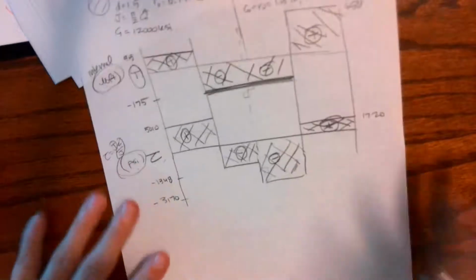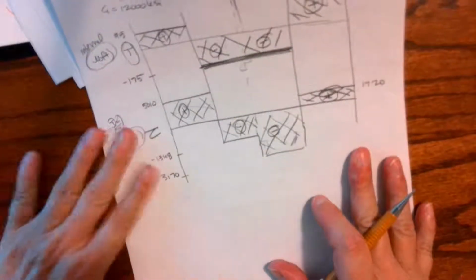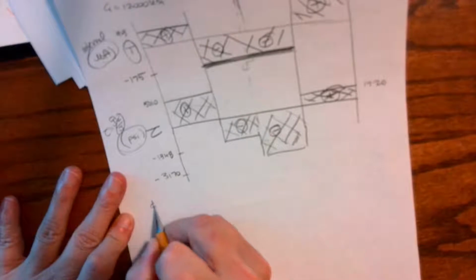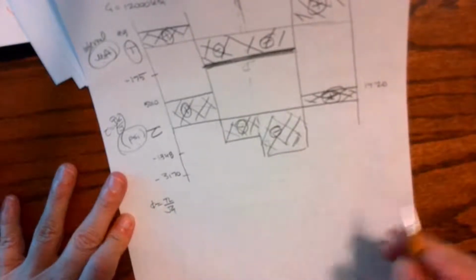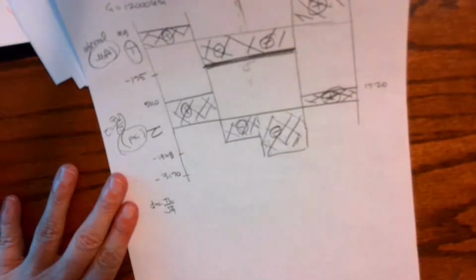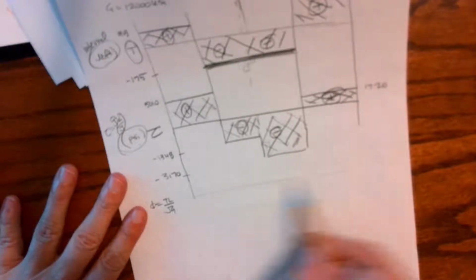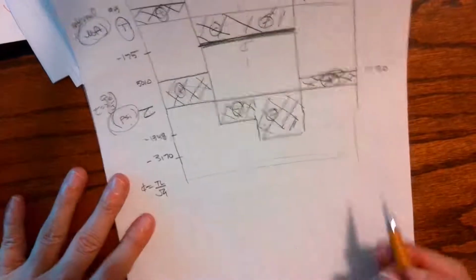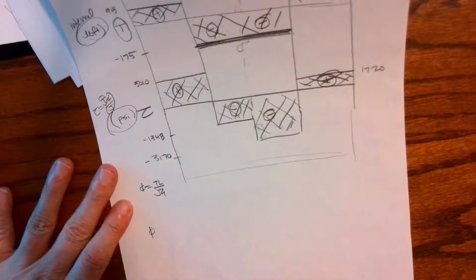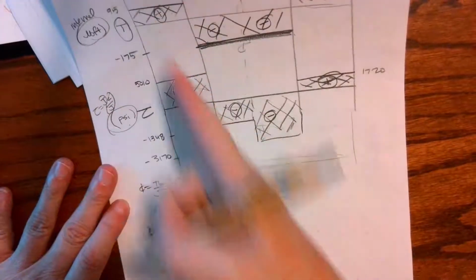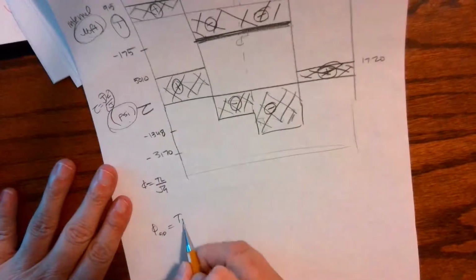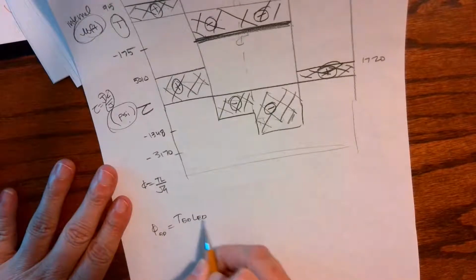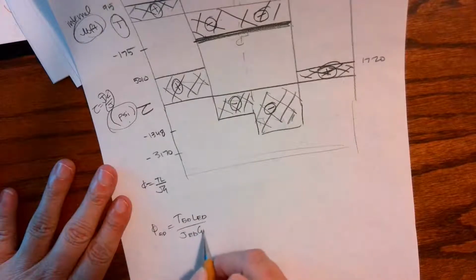Okay, so now what we need to do is find that angle of twist for each piece. So my generic equation is TL over JG. And I need to set this up much like we've been doing. And we are going to look at the angle of twist. I'm going to leave some space so we can graph out the angle of twist. But we want to look at the angle of twist of this section right here, which was E to D. And that's going to be T_ED, L_ED, J_ED, G_ED.